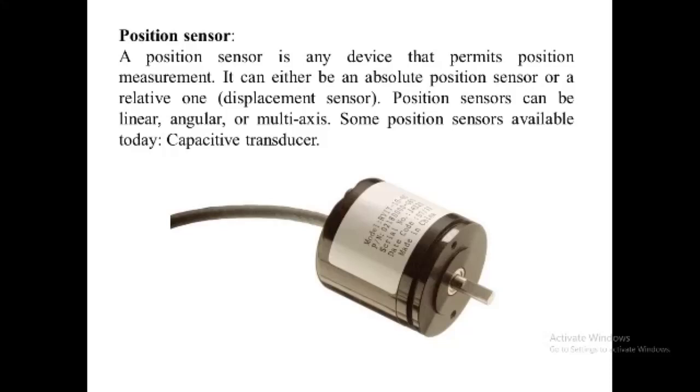The output voltage signal is taken from the wiper terminal of the sliding contact as shown. This configuration produces a potential or voltage divider type circuit output, which is proportional to the shaft position.